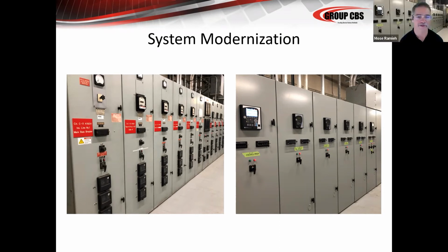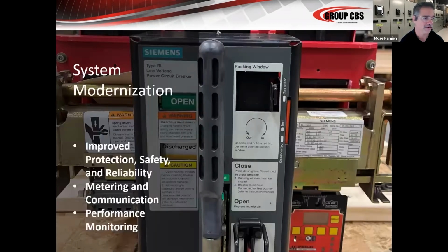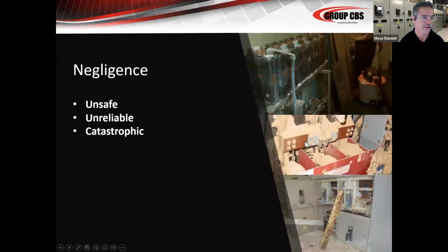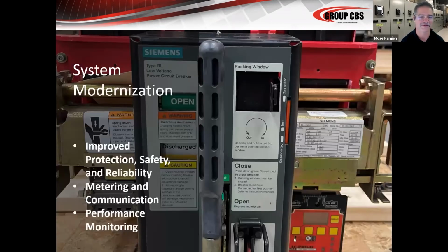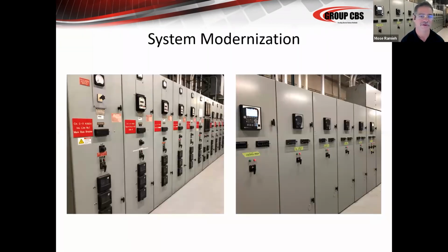Yeah, no, exactly right. And once again, some equipment's more subject to failure in those situations than others. Like the Pringle switch or the bolted pressure style switches shown here. The manufacturer says to open and close these every 6 months. So once again, it depends on the equipment. And when somebody says, hey, I got a Pringle switch and we don't know the last time it's gotten opened, I go in with all kinds of extra tools because we know we might have to pry it open the first time, clean, lubricate, operate it a dozen times to get it working again. So it does vary; equipment, condition, and criticality are important.